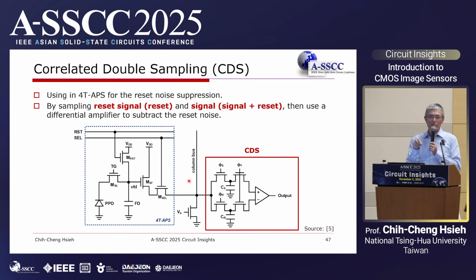Basically, it uses an in-pixel event detection circuit. And most importantly, I introduced that all the sensors need a charge accumulation phase, right? But for DVS, it's real-time sensing. There's no accumulation at all. It uses a logarithmic sensor to convert the photons to current and then to voltage directly, continuously.